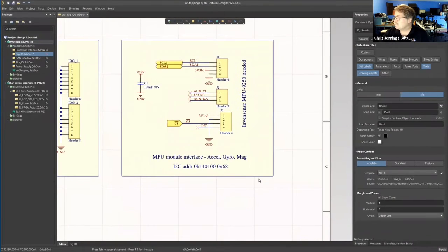And likewise here, this is a series of through-hole connectors that plug into an external module. It's an MPU 9250. It has a gyro and it has accelerometers on it. It's for basically navigation for a robot. That's what it was used for here. We didn't use the mag, because the magnetic compass gets thrown off by all the DC currents running around. But the accelerometer and gyro worked pretty well, and it was used for guidance.